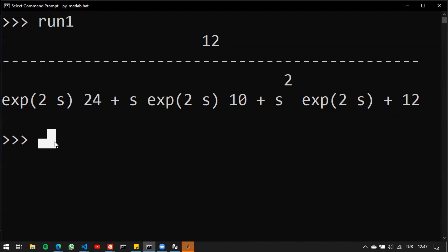So all that stuff that we've talked about, the characteristic polynomial, the stability properties, the fact that we will choose zeta and omega and assign them certain values and try to increase the dominance factor, all that stuff is not applicable to this system because we don't have any polynomial here. We have a nonlinear term, and that's it. It's depending on a frequency variable s, but that's the only thing that we have.